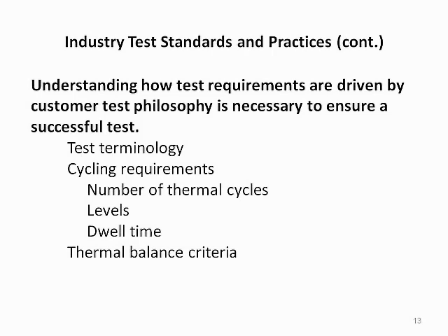Understanding how test requirements are driven by customer test philosophy is necessary to ensure a successful test campaign. It's important to have a thorough understanding of the customer's test terminology, temperature cycling requirements, including the number of thermal cycles, temperature levels and dwell time, and thermal balance criteria. All of these will be discussed at various points during this lesson.